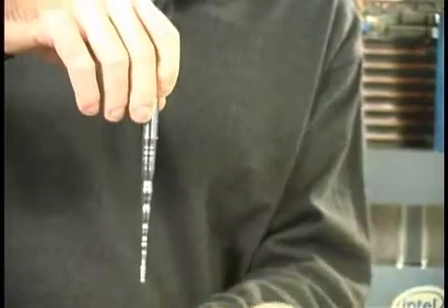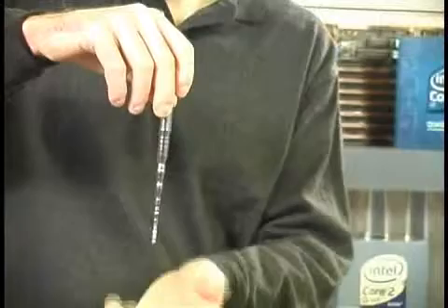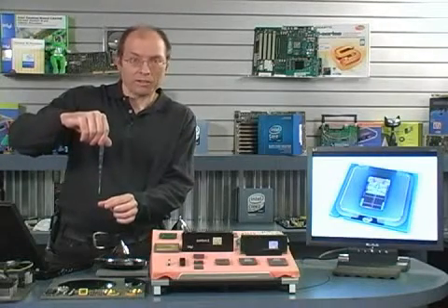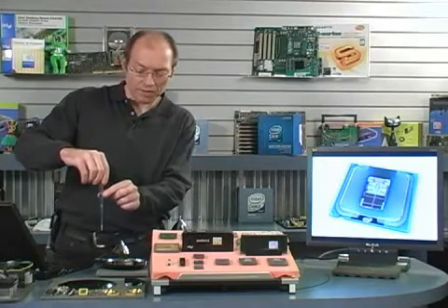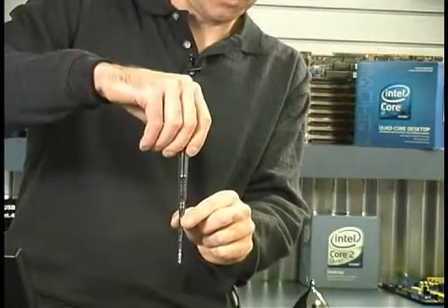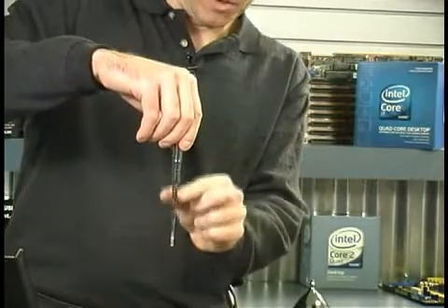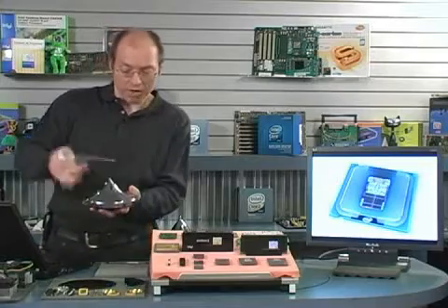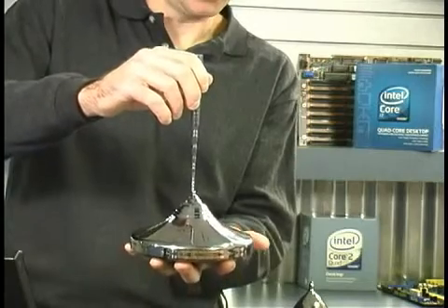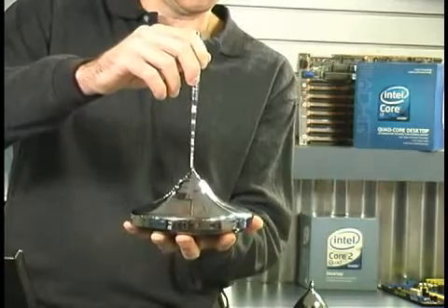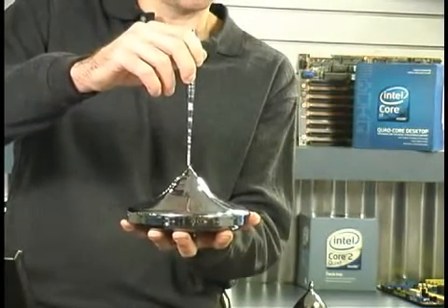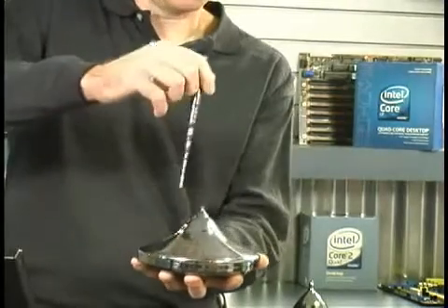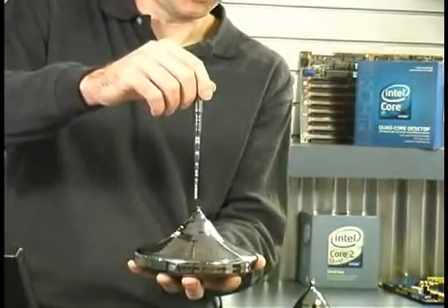Now, if you imagine this vat of molten material, it's kind of like melted glass. It's sort of thick and taffy-like. And as the crystal begins to pull out, some of the material sticks to it and begins to harden. So this seed crystal pulls out of the vat, and you can see a bunch of material sticking to it. They pull at first rapidly until we have a very thin stem forming, and then finally more slowly until a wider and wider crystal begins to emerge from the vat. This is an example of a pure silicon crystal that I have here that was grown in one of these vats. As you can see, the shoulder of the crystal gets wider and wider as it is pulled out. This is like millimeters per hour. It's a very slow process.